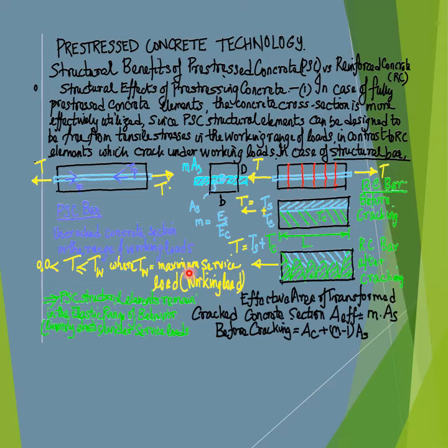In other words, the pre-stressed concrete bar, that is the most elementary example of a pre-stressed concrete structural element, can be designed to remain uncracked in the elastic range of behavior, or the linear elastic range of stress strain behavior, under service loads or working loads.